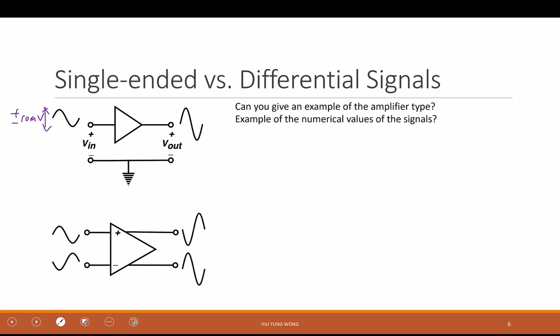The AC ground, however, right? We're talking about the AC signal, right? So if you remember common gate, right? We usually would say we bias it at 2 volts, for example, and then you go from 2.01 volt to 1.99 volt, right? And that is the plus minus 10 millivolt. Right? So now we just look at the small signal.